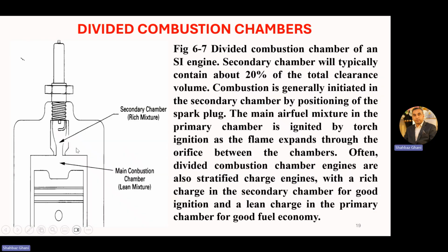Let's see. We have this is your cylinder, this is your piston, and this is your main chamber. And this portion here is the secondary chamber. The main chamber comprises 80% of the clearance volume, and this secondary chamber in this portion occupies the 20% of the clearance volume.